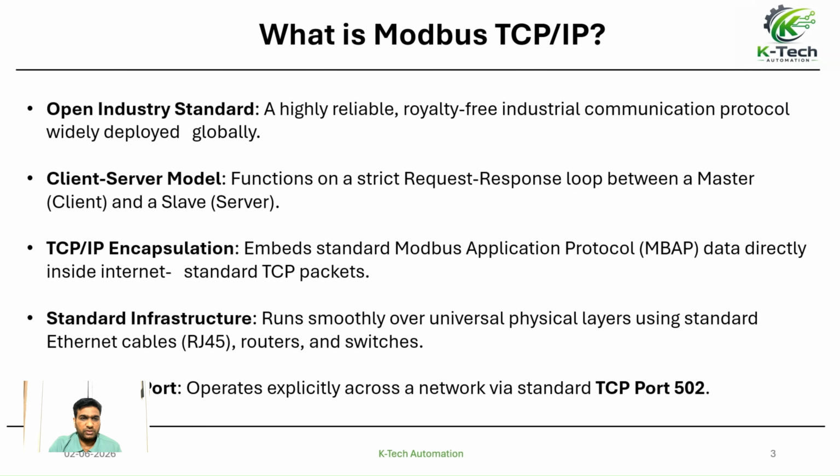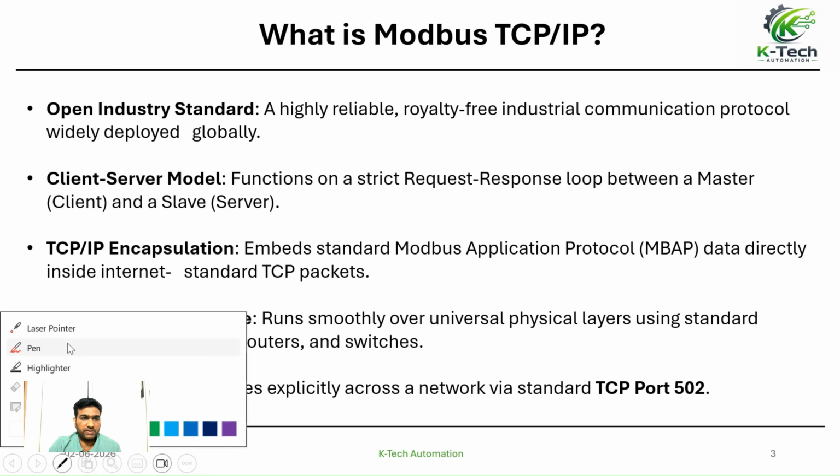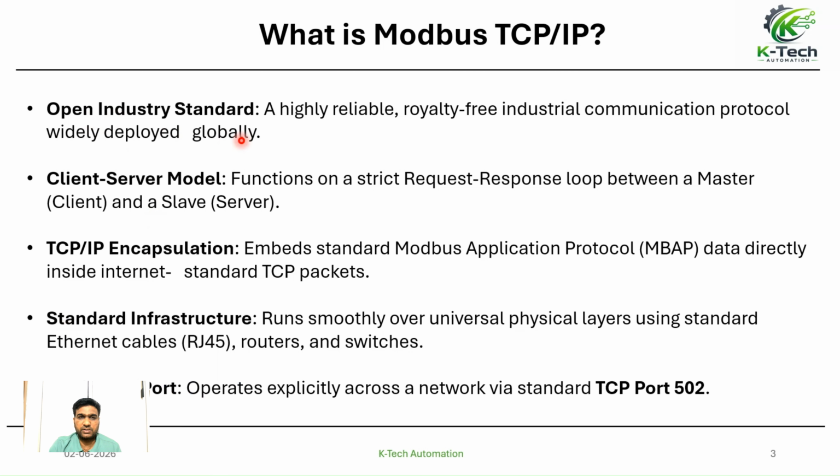So about the protocols, what is Modbus TCP? Modbus TCP is an open industrial standard. This is an open protocol, which means it is a royalty-free protocol, so there is no need to pay for it, and it is globally used. It follows the client-server model, the same type as Ethernet. The master is a client and the slave is a server. In this case our PLC will act as a server.